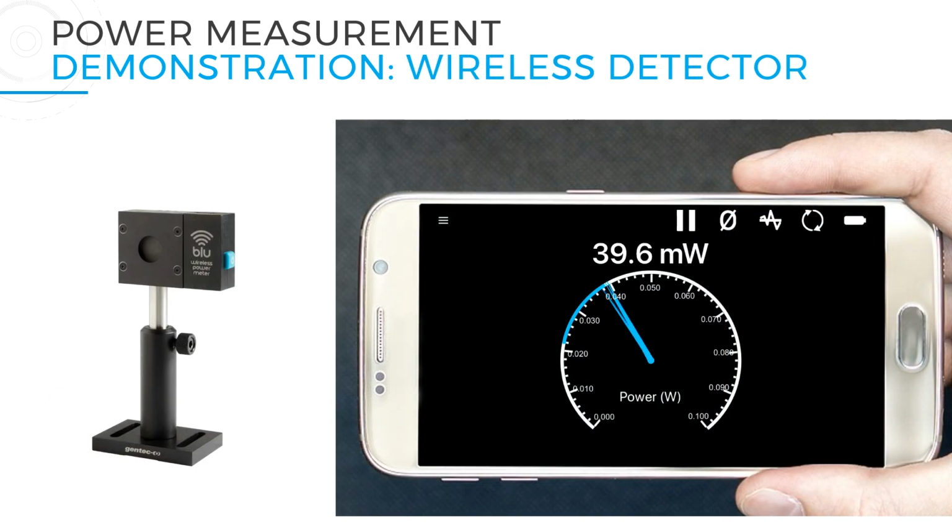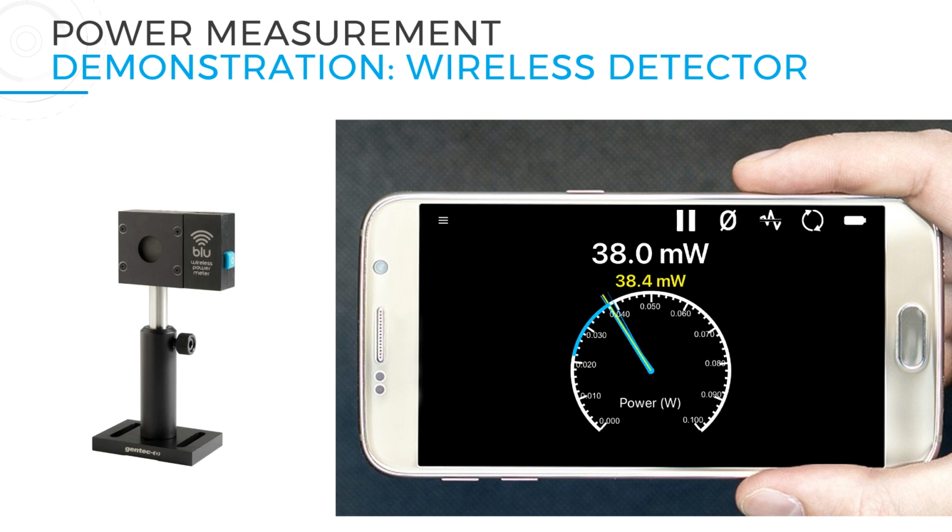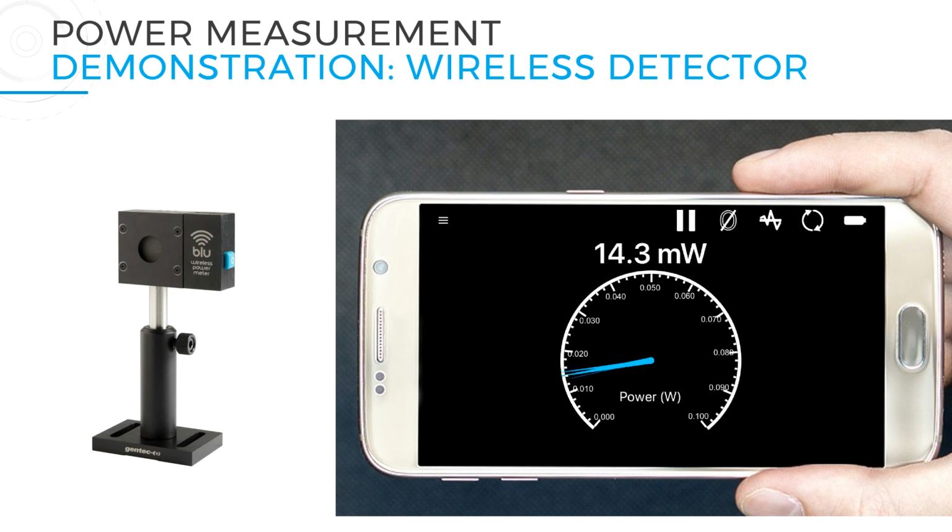Last but not least, this is a Thermopile detector connected to my smartphone via Bluetooth. Our green laser is warmed up, so is my detector, with around 38 milliwatts. Blocking the laser to do the 0, it's good to wait a little bit, because reaction time of a thermopile detector is longer than a photodiode. So let's wait a few seconds before pressing the 0 button. There we go. All right.